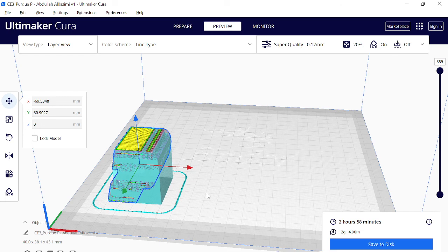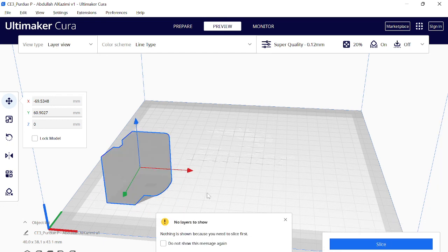So in this case, if we choose to print the P vertically, it needs supports to hold up the top part of the P. That's why you'll notice the whole thing is nested in this blue shape, right? We can't let it print just the P because it'll fall over. So we have to print the whole thing in a block so that it has the structural support to stand up. This is honestly a pretty bad example of how to print, so I'm going to go back and change it.